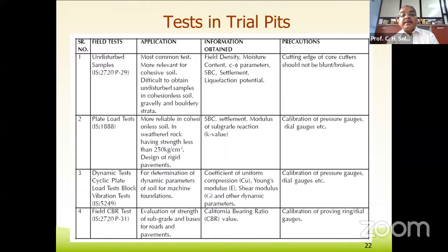Plate load test can be conducted in the trial pits. Dynamic test. This dynamic test has been described in IS 5249, where two methods are described in detail: one is the cyclic plate load test, and the second is the block vibration test. How to find the coefficient of elastic uniform compression, used for the design of machine foundations, is described in IS 5249. And the field CBR test can also be conducted in the trial pits.